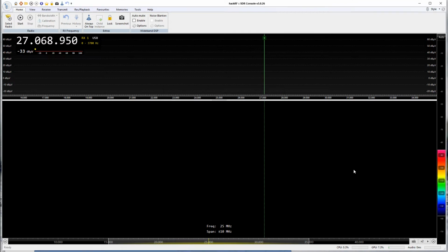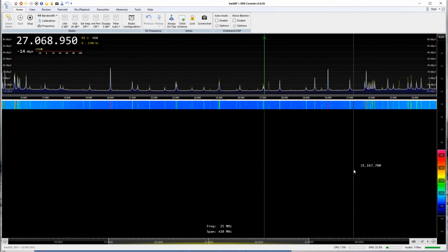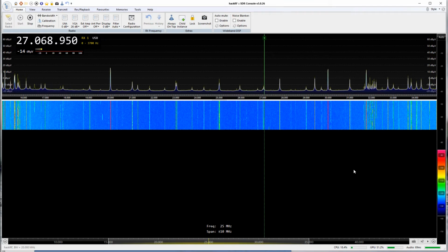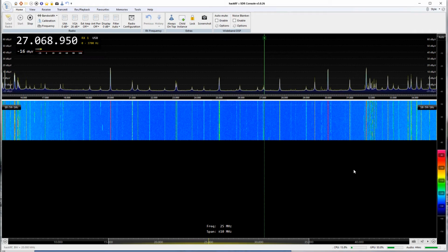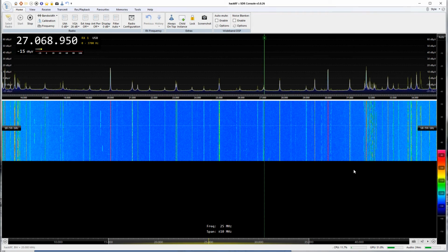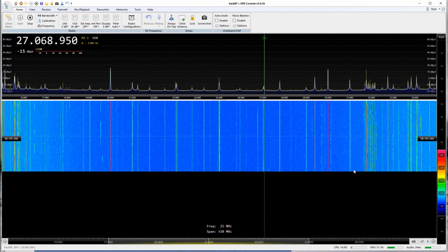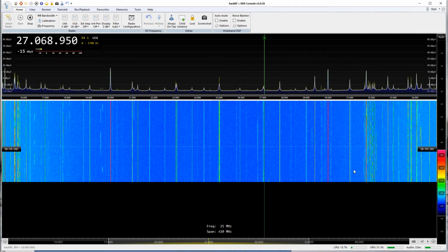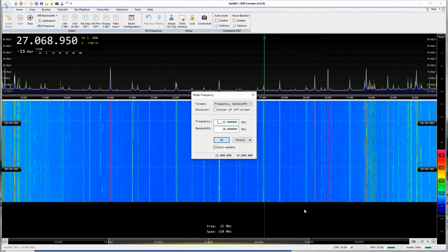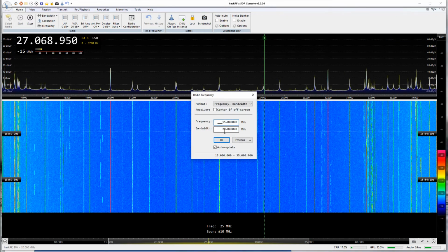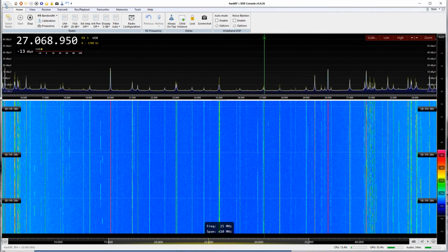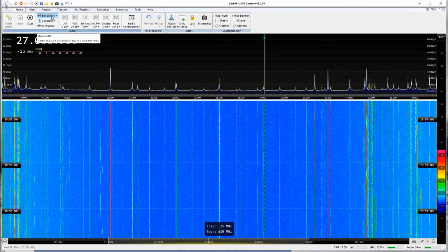In most cases, Radio Jove focus is in the 15 to 30 MHz range. Other ranges can be selected depending on your SDR bandwidth specifications and project requirements. Be aware that selecting very wide bandwidths in the 30 to 50 or greater MHz range may be more than your computer resources can handle, especially at high bit rates.